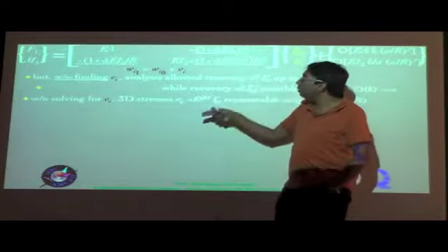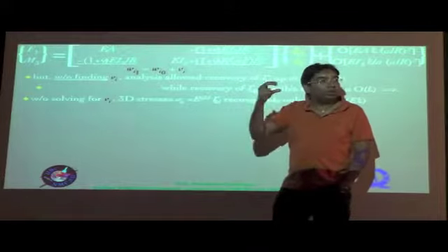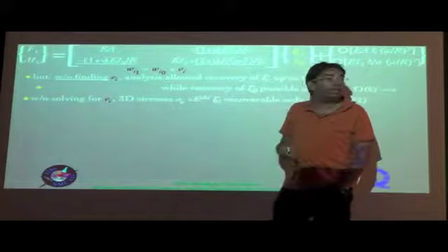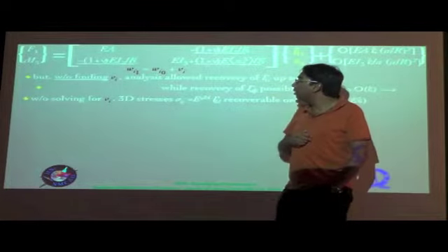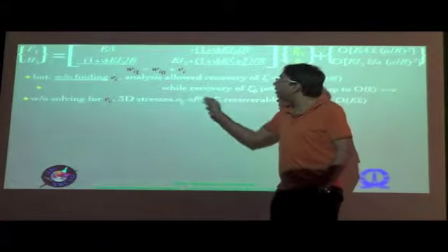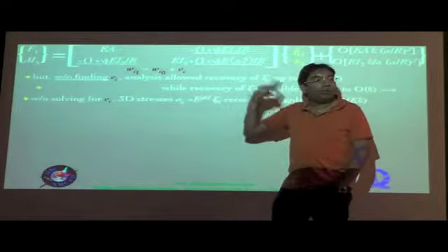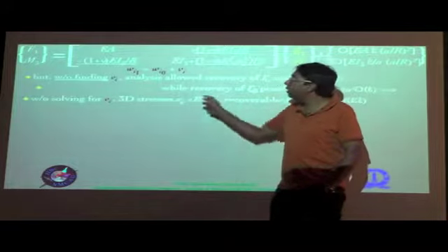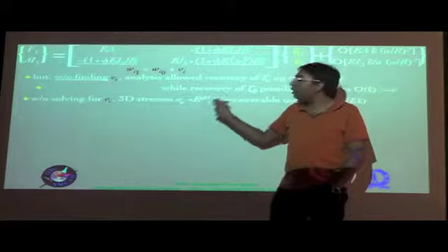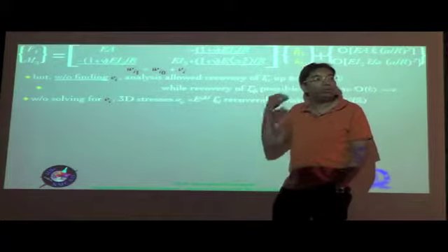In the case of the isotropic material, of course, it's a homogeneous isotropic material that we considered, so the Eijkl would also be fairly simple tensor components that we would have to deal with. But even in a generic case, even when we go to composites, we would see that the 3D recovery would eventually be done for the stresses by using the 3D stress-strain relationship or the constitutive law, which depends purely on the material alone.